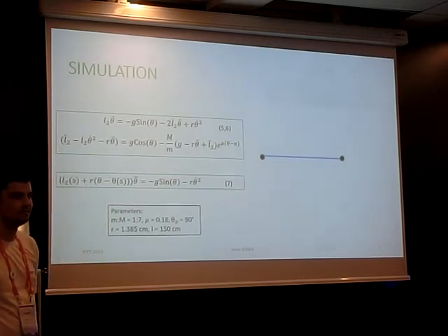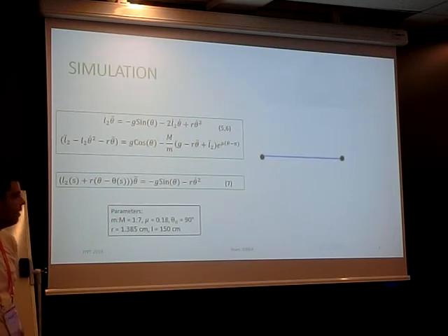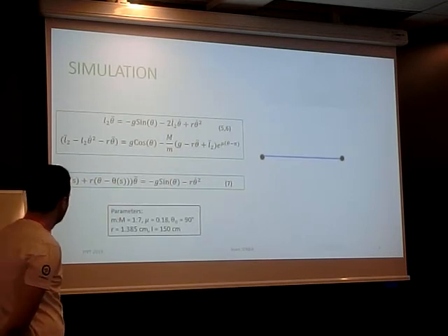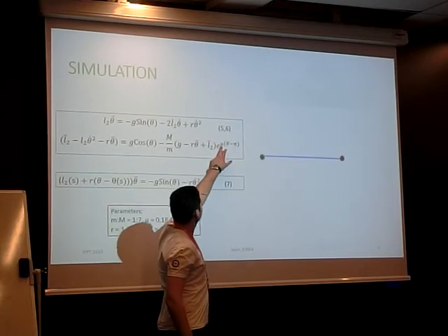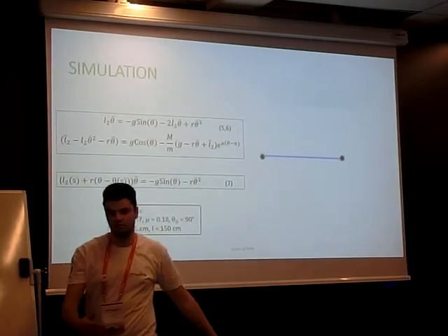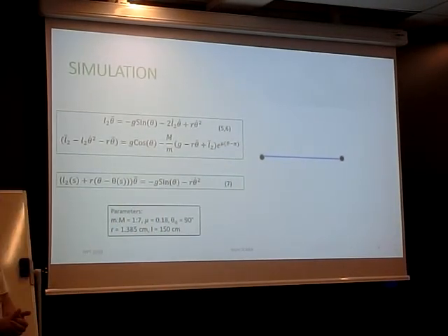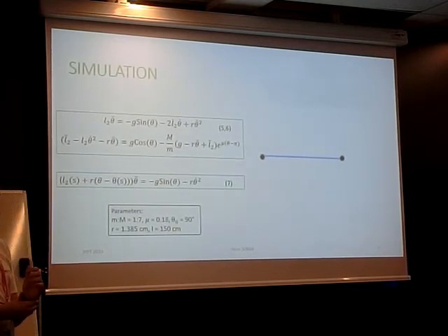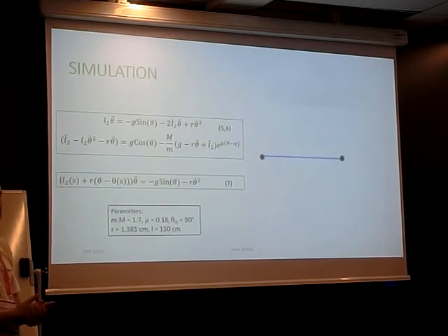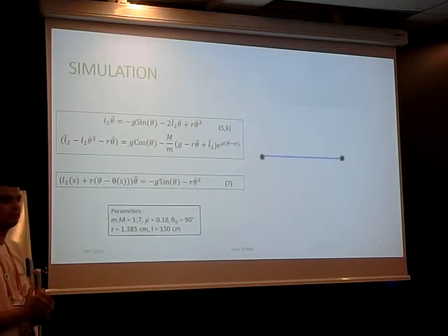For the reporter, can you point out the term for the friction between the rope and the rod? Yeah, this is this part. We only have this friction coefficient, and we need to go back to see where it came from, from the first equation. The capstan equation is the source. So, opponent, do you agree with the reporter that he used the exponential term from the capstan equation for the friction between the rope and the rod, and Euler's formula for friction between the rod and the spring? Yes, I agree with them.